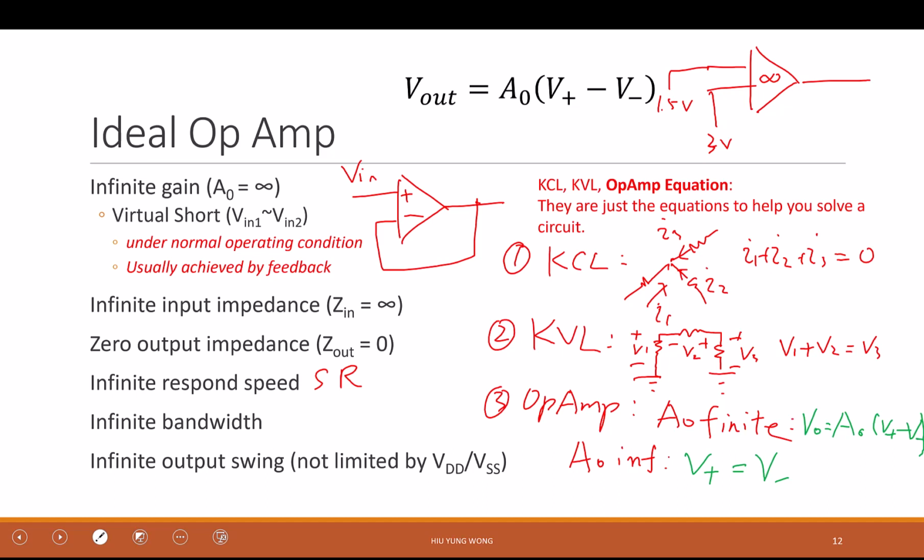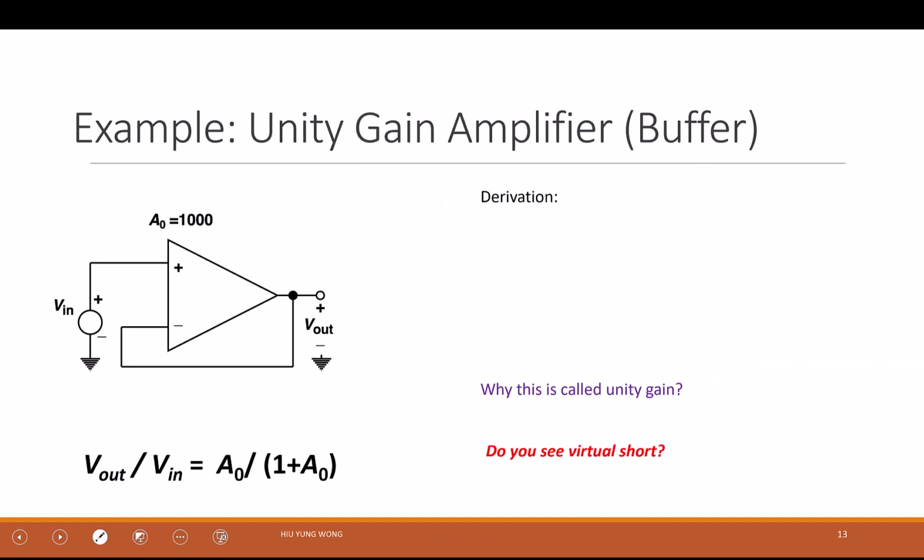For example, you say a resistor is very large. Fine, because all other resistors are only about 10 ohm, 100 ohm in this path, but this path is almost 1 mega ohm. When I do my equation, I can treat it as infinity. But if the rest are actually 1 giga ohm, you better treat this as a short. Same for infinity and ground and zero. If you play with these two numbers well, it simplifies your life a lot. But if you do it wrong, everything will be wrong. Okay, so after this, we can actually start doing something difficult.